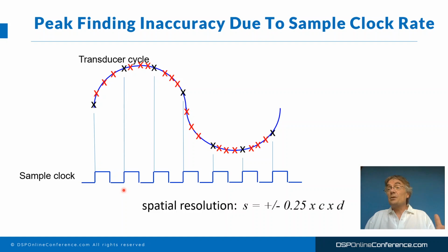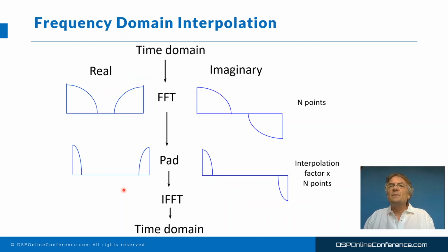So a very similar process to the overlap and add, overlap and save type of thing. We've got time domain data coming in, fast Fourier transform, doing some processing, inverse Fourier transform, time domain data coming out that is now interpolated. And again, the key thing here is the massive improvement in the number of MIPS required to implement this process. There is a latency increase, but it's a block-oriented application anyway, so reducing the MIPS reduces the cost.